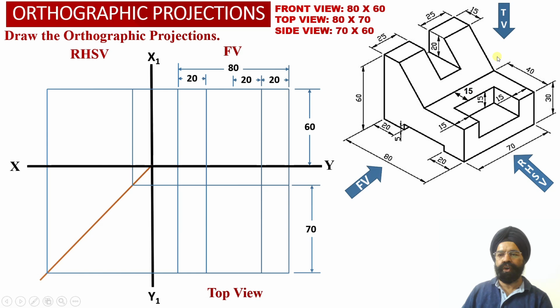And further we know that we can divide this solid into two elements. Element number one is a horizontal web which is lying at the base of the solid. Then there is a vertical inclined web which is resting on top of this horizontal web over here. So this we are going to term as element number 2. Into element number 1, we have already worked out this rectangular slot location over here.